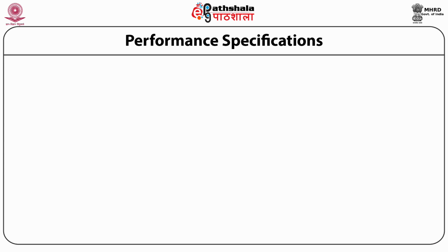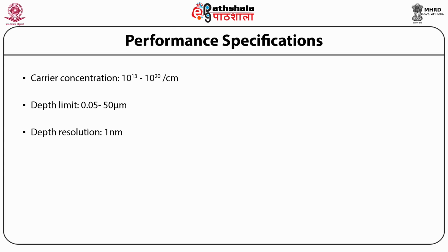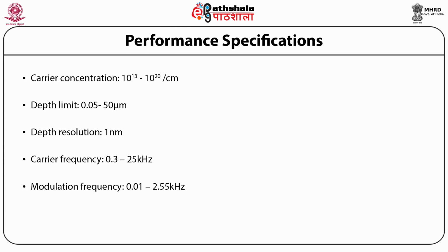Performance specifications. Carrier concentration is 10^13 to 10^20 per cubic centimeter. Depth limit is between 0.05 to 50 micrometer. Depth resolution is 1 nanometer. Carrier frequency is between 0.3 to 25 kilohertz, and the modulation frequency is between 0.01 to 2.55 kilohertz.